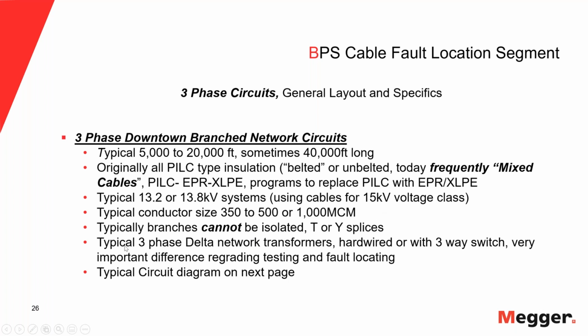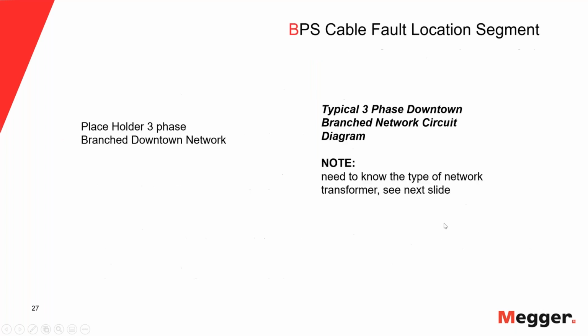In addition to it, most of the network transformers that are used are delta transformers. And again, they could be hardwired or they could have switches in them. I'll talk about that in a moment a little bit more. But whether they are hardwired or they have switches makes a difference in what we can do in terms of fault locating.